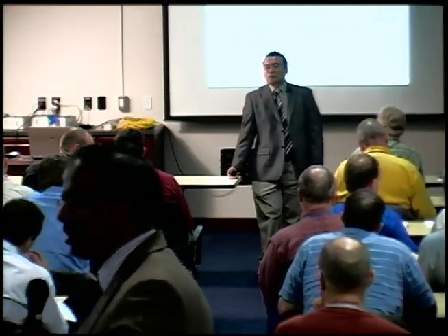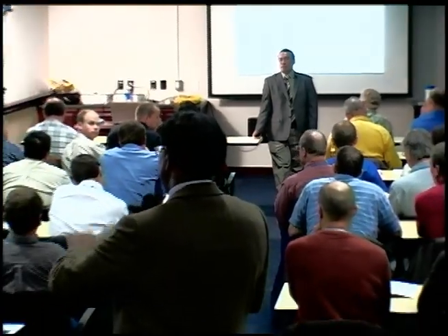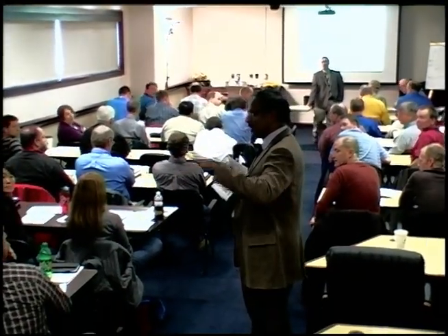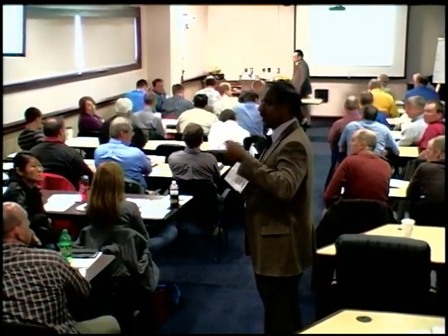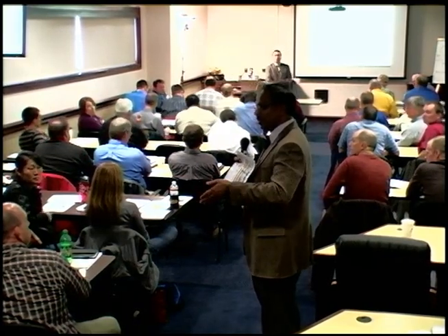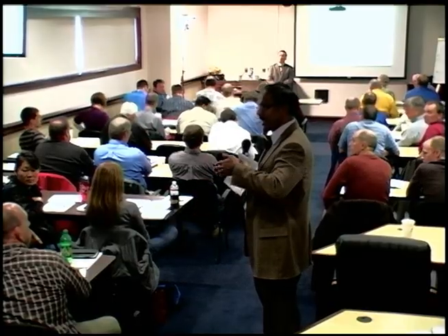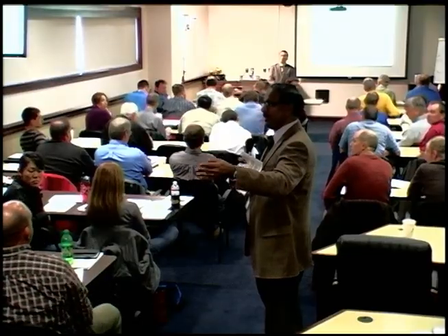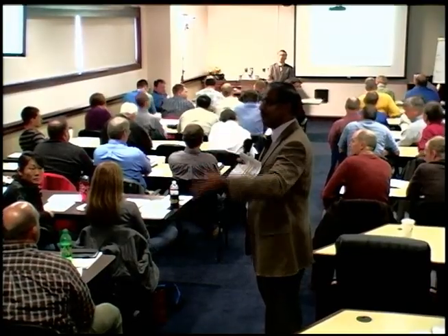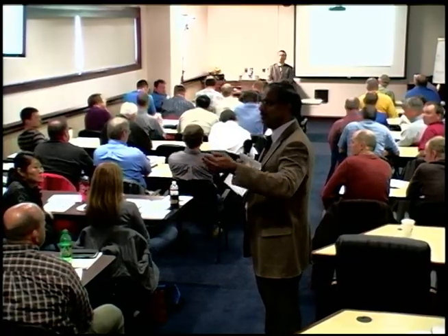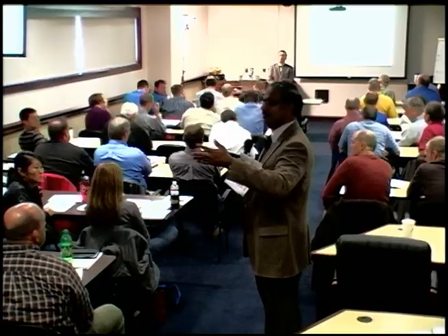Dean is a structural engineer, and those of you who are structural engineers, I'm a structural engineer, so let me try to address it differently. Unlike what we typically do for structures, here, depending on the method you choose, your capacity changes. So we are using the Blue Book for the design because that's what, as Cam said, was found to be the most efficient. So you get one value. If you turn around and use a different method, you get a different capacity. Because you get different capacities for the same problem, when we back calculate a resistance factor, they vary, giving various numbers.